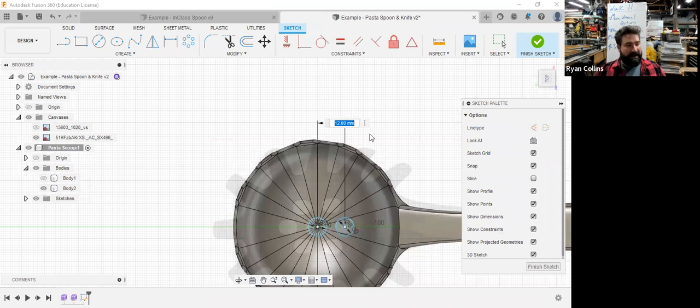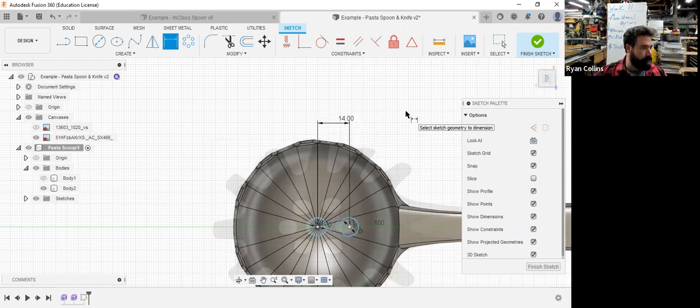What if I say, oh, you know what? That actually should be a little bit different. Let's say that should be 10 millimeters away from one another. It just moved the circle around. If you want to adjust it, double click. Maybe let's make that 14 instead. Just drags it in and out. All right. Hit enter. I'm just trying to change that. Oh, let's hit escape instead. It's not doing so. Go to create, or I was just going to use the circle pattern.